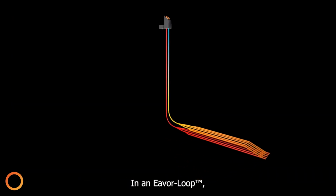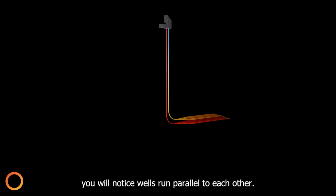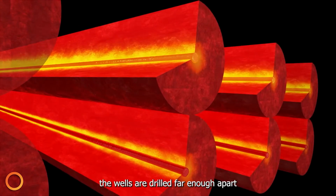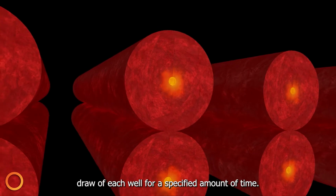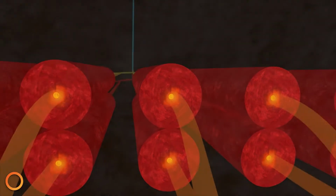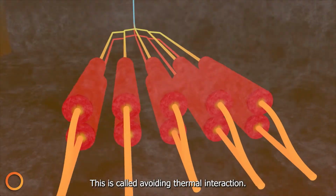In an Eavor-Loop, you will notice wells run parallel to each other. In this situation, the wells are drilled far enough apart so as to not significantly affect the heat draw of each well for a specified amount of time. This is called avoiding thermal interaction.